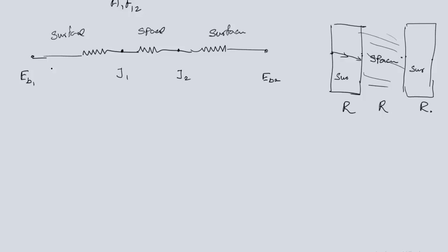You know the formula for surface resistance, which is 1 minus epsilon 1 divided by A1 epsilon 1. Similarly, here also surface resistance, but it is for surface number 2. This is surface number 1, this is surface number 2. So 1 minus epsilon 2 divided by A2 epsilon 2. Here it is space resistance. You know the formula, 1 divided by A1 F12, right? This is the electrical circuit for two surfaces.